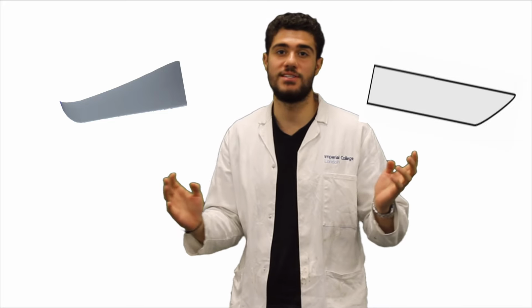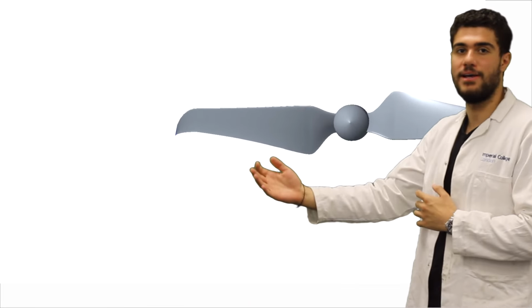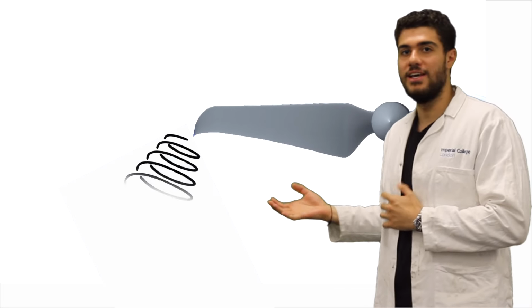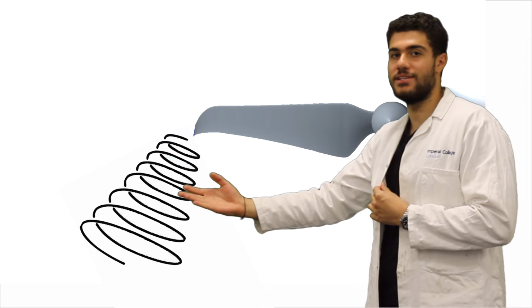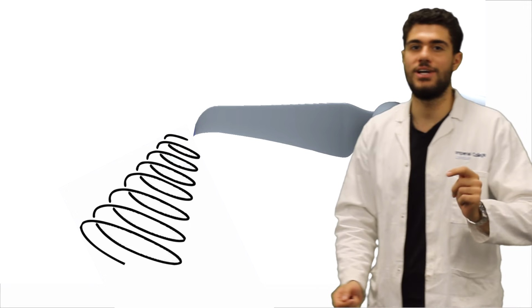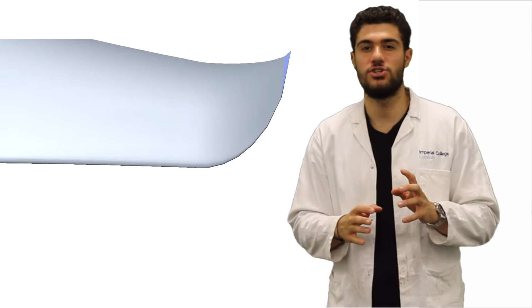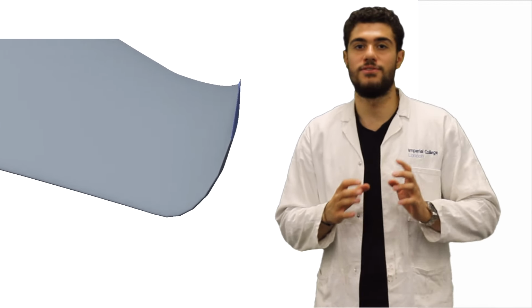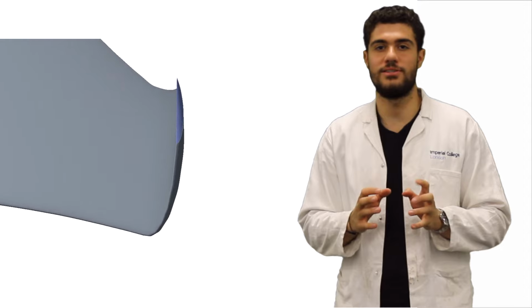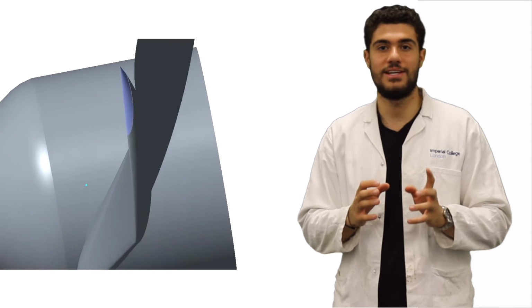Both the Horner tip and the Shark tip mitigated the effect of vortices as they increase the effective wingspan of the aircraft, as the formation of vortices is delayed and moved horizontally outwards from the center, resulting in a decrease in downwash and reduced drag. Both tip designs are very similar, but given that most of the applications we found for the Horner tip involved static wings, we decided to opt for the Shark tip instead, which is heavily considered and tested in relevant wind turbine applications, and hence thought to offer the best design.